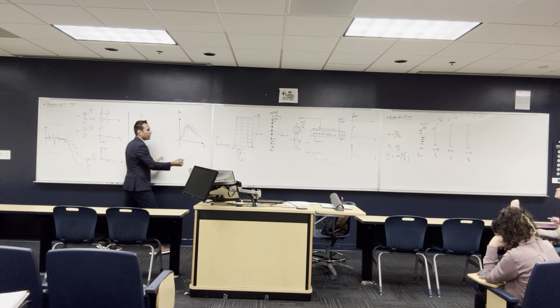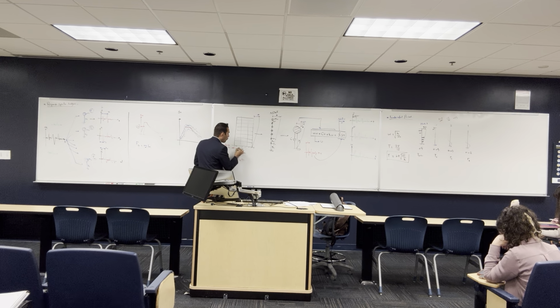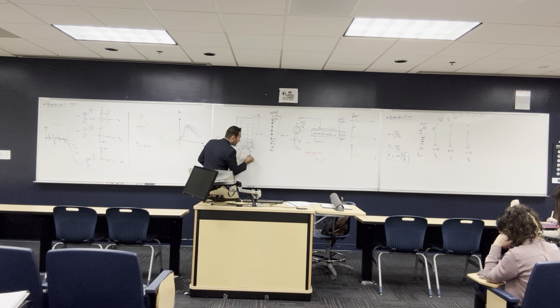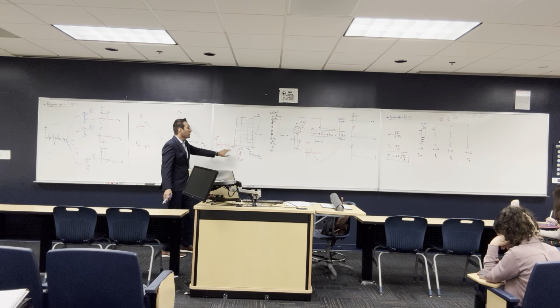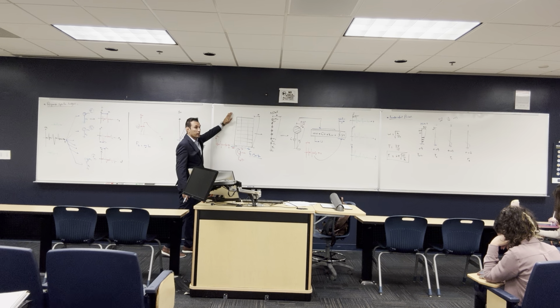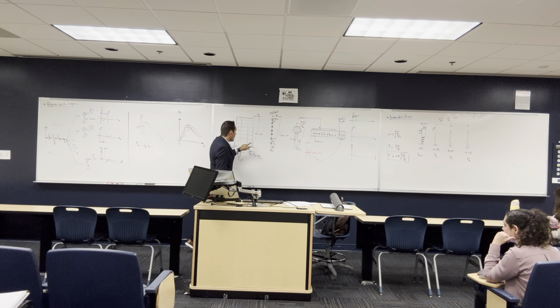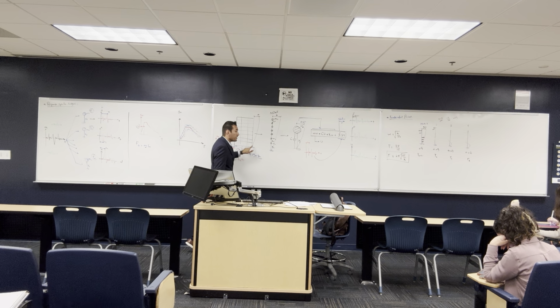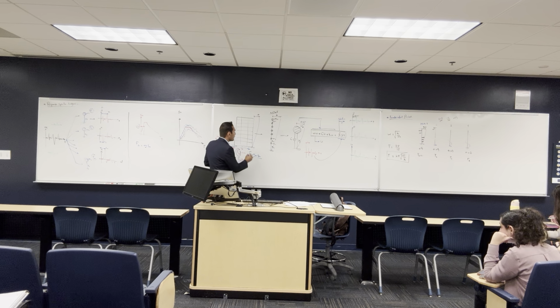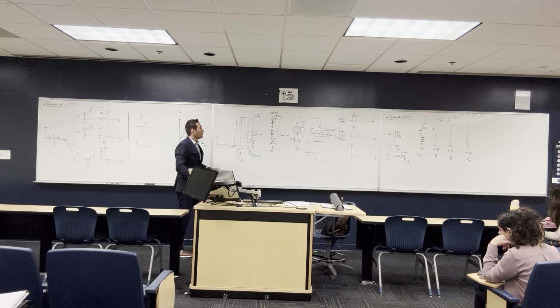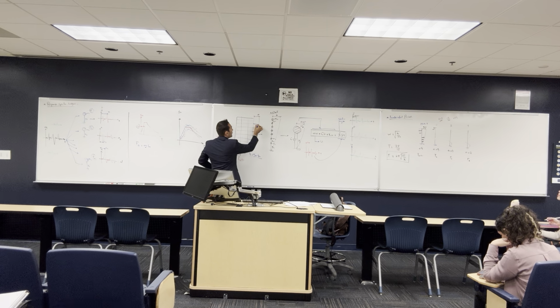Once you know exactly the force that hits the base, 500 ton or something like this, I distribute these forces on the stories in a way that can develop the deformation. Every story is gonna take a piece from this 500. How can I define this? It is based on the mass of the story and the height of the story from the ground. This one is gonna take a force, this one is gonna take more. The higher it is, the more it is gonna take from this force. And there is a rule that we can use to do this.